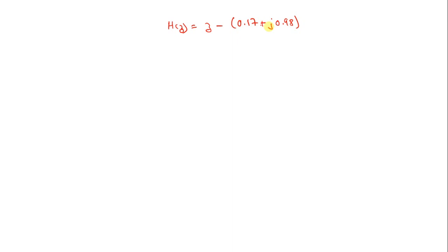Then another was that the number of poles should be greater than or equal to the number of zeros. So here we only have zeros. Where is the pole? Is it a realizable filter? It is not a realizable filter. So what should it be? It should be z minus 0, that means z.